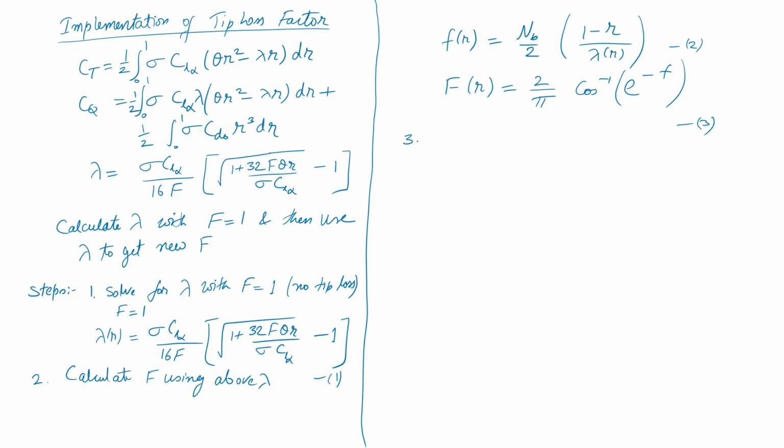Yeah, so sin phi is lambda by r. That is why I said you can write it like this also. If you want, you can use the sin one also, that is not a problem. The only thing is you cannot then multiply with r. So phi will then be lambda by r. Because my inflow angle will be very small, I can always approximate sin phi with that, and I can write it like that.